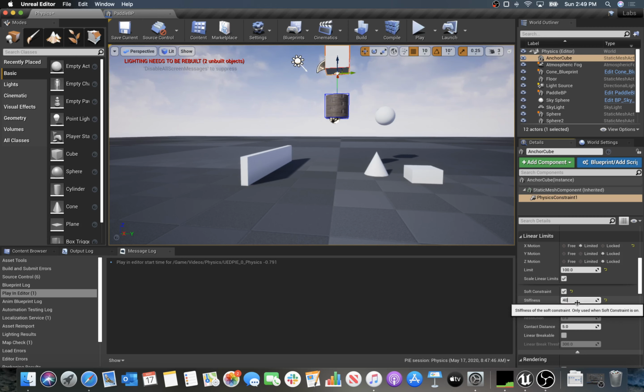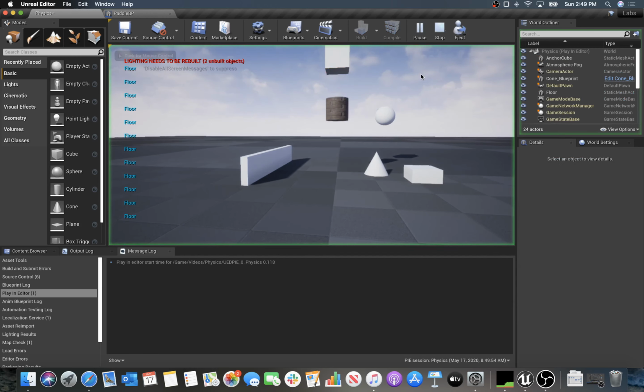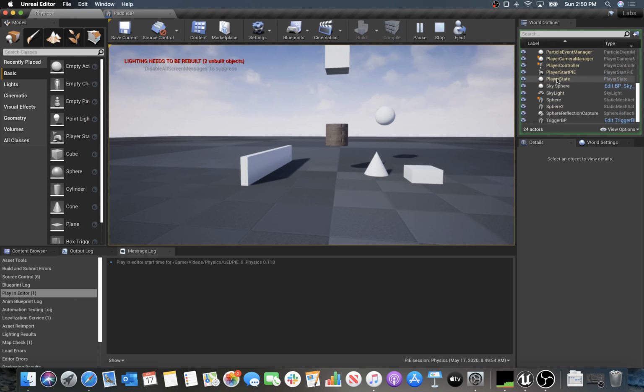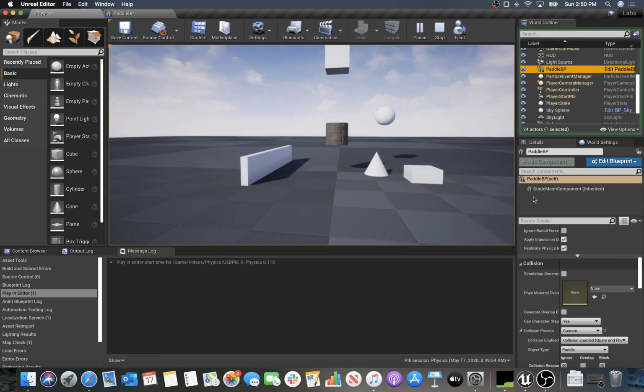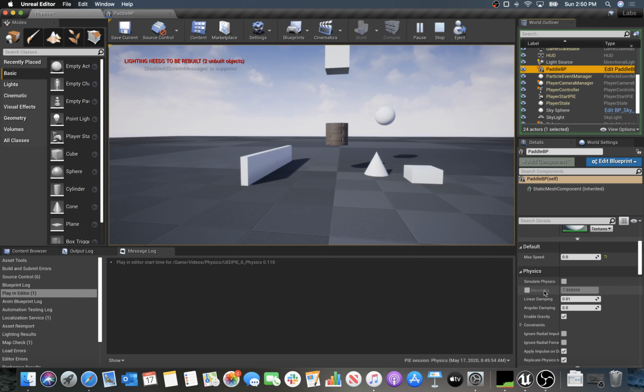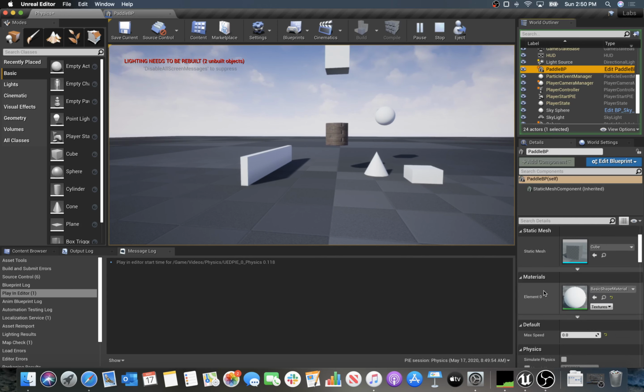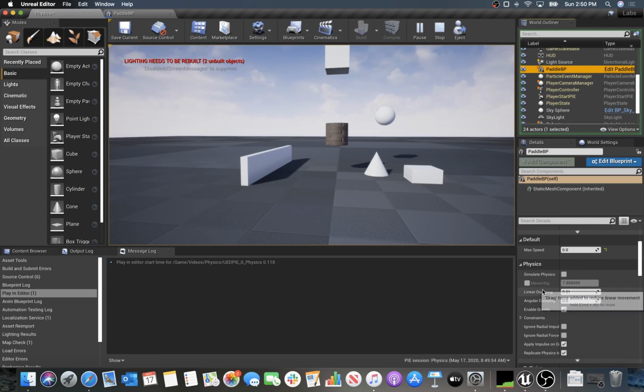This is all going to depend on the weight of the object, which is based on basically the volume of the mesh and some standard density. And so when I hit play, what we want to see is it sort of bounce like this, so that when our paddle, which I've turned off temporarily, starts rotating, it can hit it. And it won't be doing too much teleportation through it.